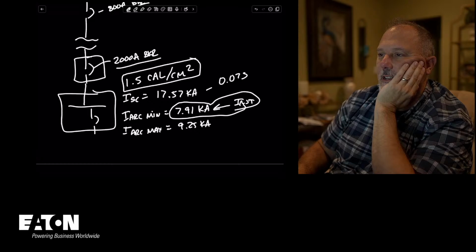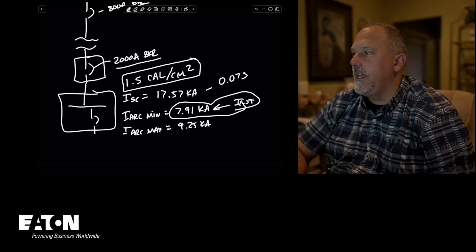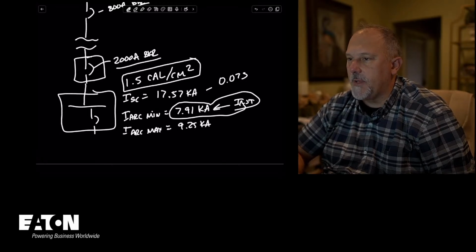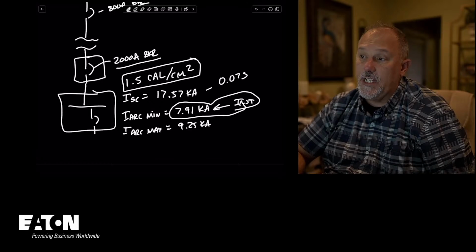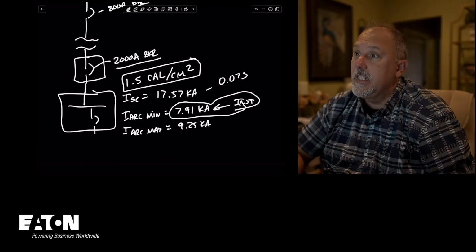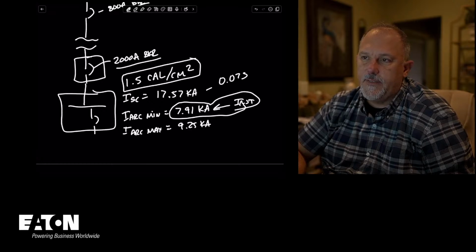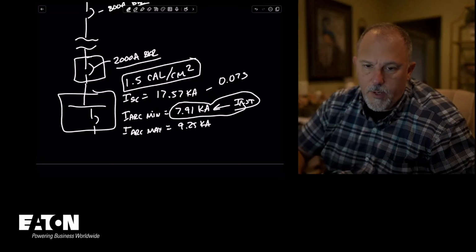Look at that. That's 0.07 seconds. 5, 6, 7. Let's take a look at what it says. There's a memory effect that can shorten the long delay. The instantaneous settings have conventional 100% plus or minus 10% pickup points. For additional curve tolerances, contact Eaton. Total clearing times shown include the response times of the trip unit, the breaker opening, and the quenching of the arcing current. So I have a feeling it'll go faster than 0.07 seconds, but that's what it is.